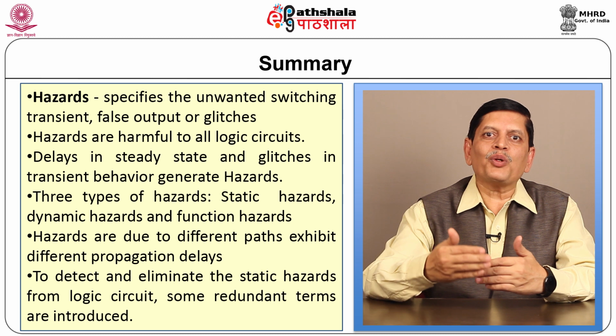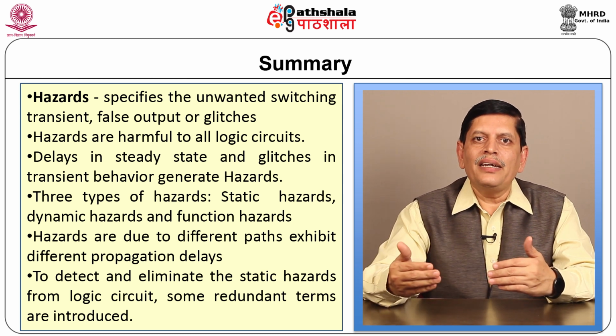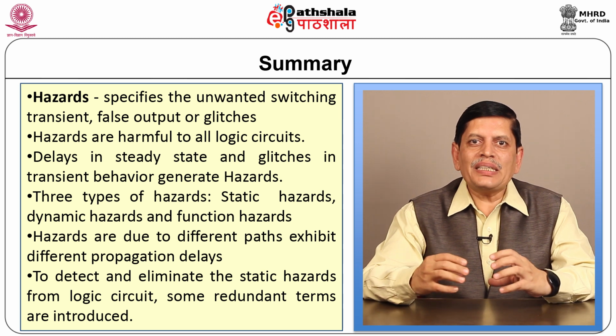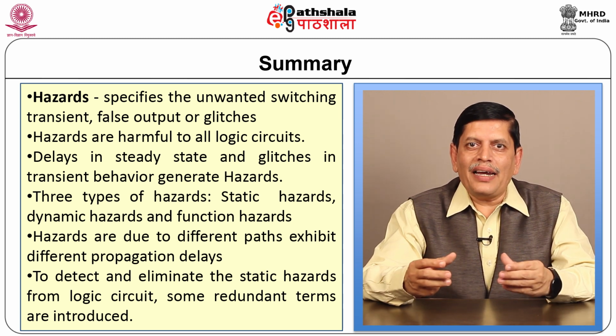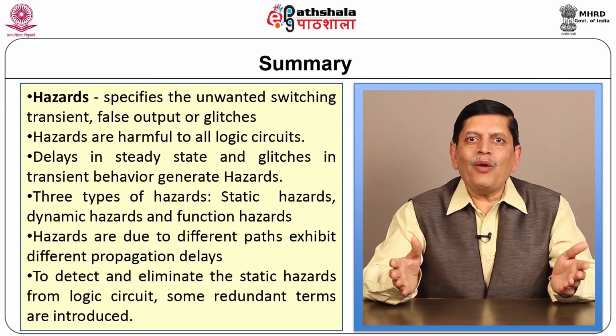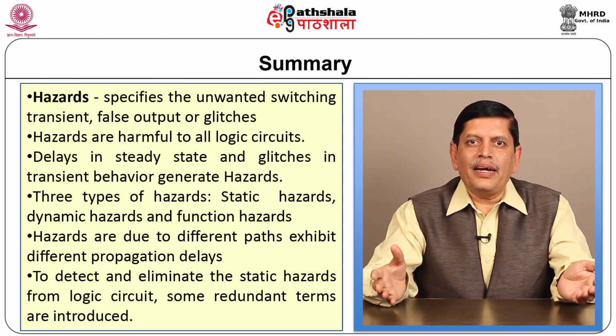We have discussed the procedure for eliminating the static and dynamic hazards, wherein we have added certain redundant terms in such a way that they will compensate for the delay. This is the way we can eliminate the hazard.